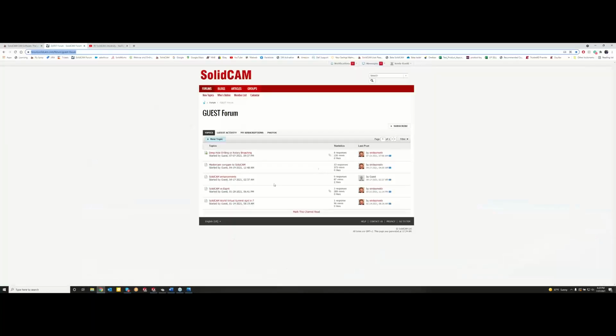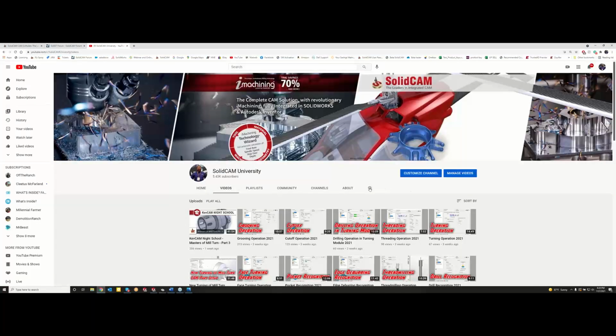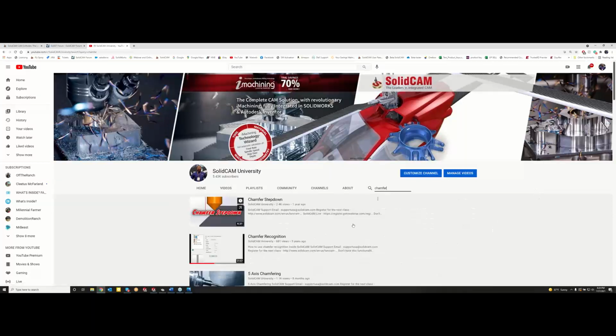And we actually have, I go to chamfer here, step down chamfer. So this is the exact video that I'm talking about. So right here, it walks you through step by step. And actually, I think we did, or Mark did this one as a profile op. Yeah, he did this as a profile op using the offset feature with the angle there. So this is how you can set it up very easily and get that larger chamfer that's there for you guys. So that can help you out, Yancey.